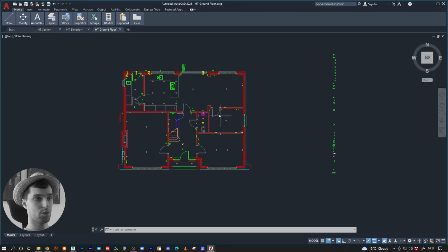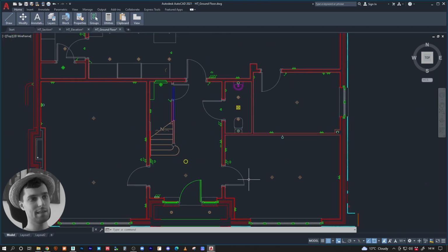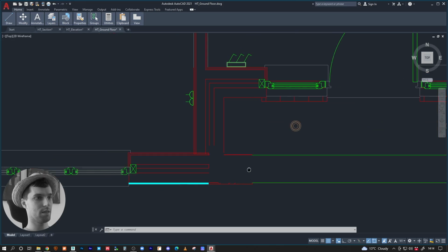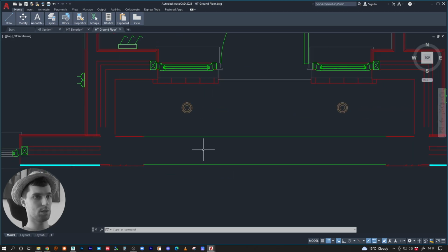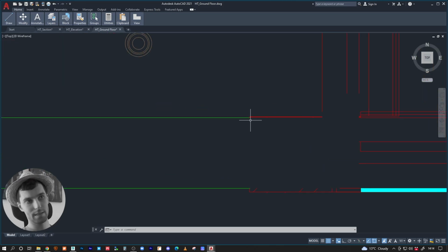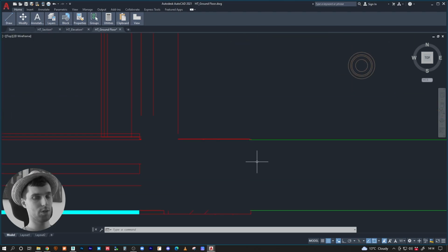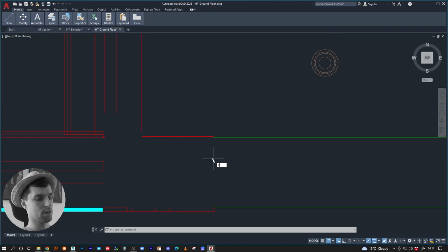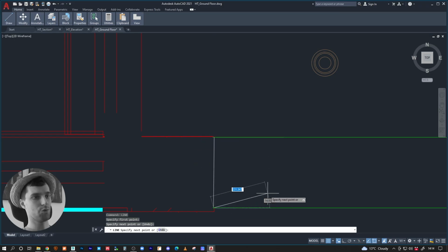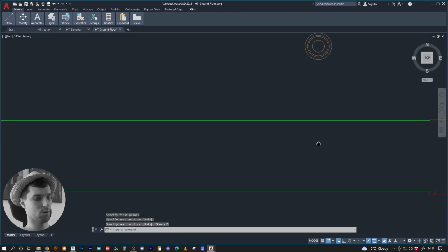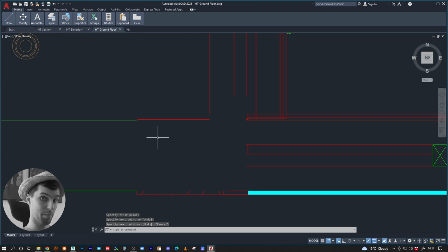So the next thing you want to do is, I cleaned enough things for me to understand what I want to clean. So for example, if you accidentally deleted a line, because I know that there is a line there, you can go back, or you can just type line, press space, and just for yourself connect it, right? So I'm gonna press space again, because space literally repeats the last previous command.